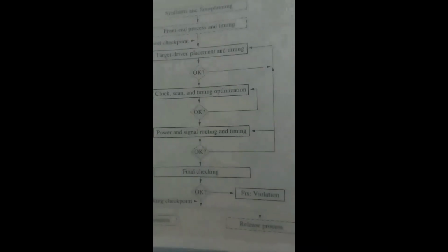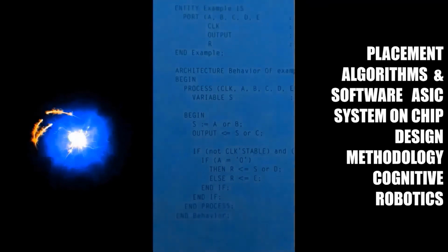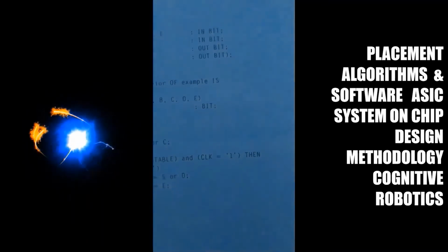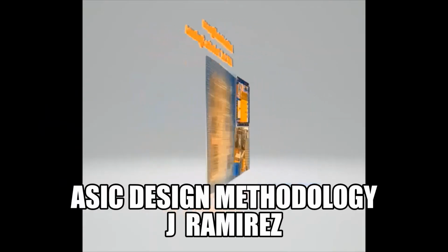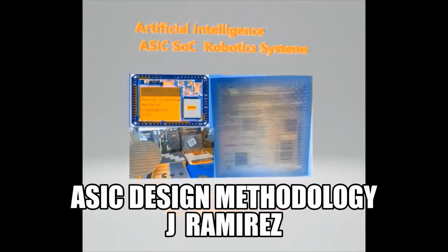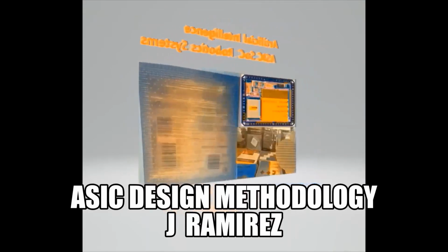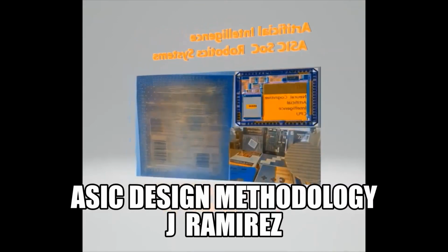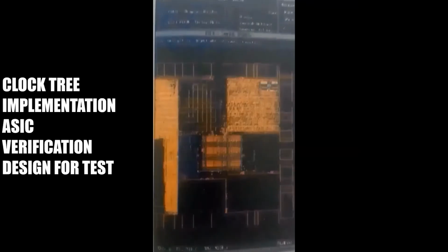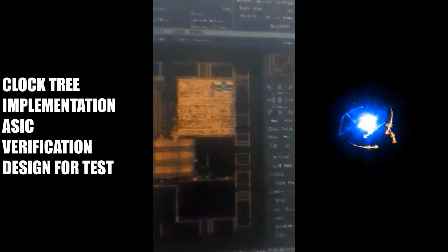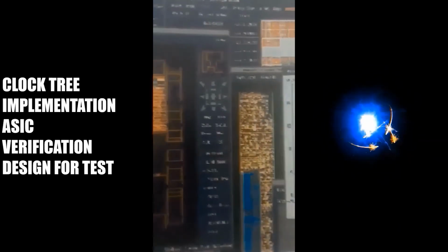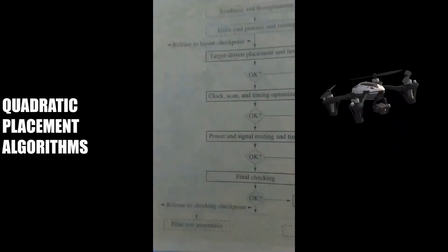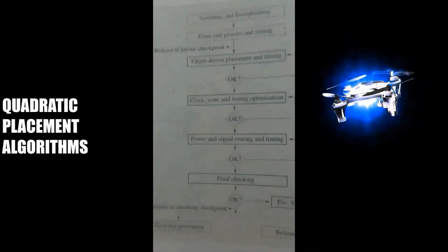Placement can be used at several points in the design process, and different algorithms are correct depending upon the state of the design. Placement is often run before the logic has been finalized to obtain an early indication of timing and wireability. At this point, the feedback may be used to influence logic changes. This may also be the time at which the locations of large objects are determined.